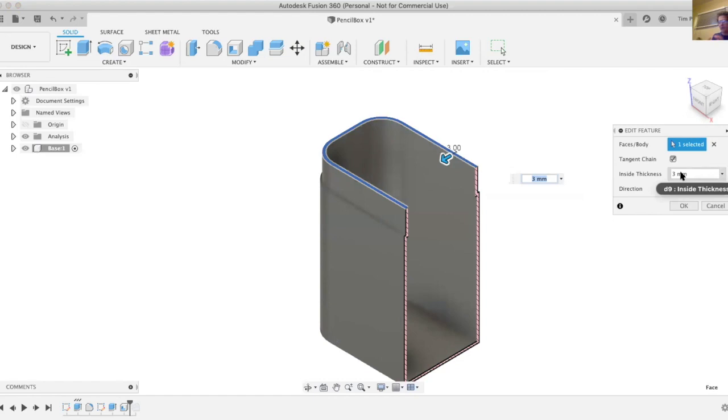So, you can define a part as a series of surfaces and then add thickness, or you can design a part as a solid and then shell it out. Either way, you can get a specified wall thickness in a fairly complex shape with multiple surfaces involved.